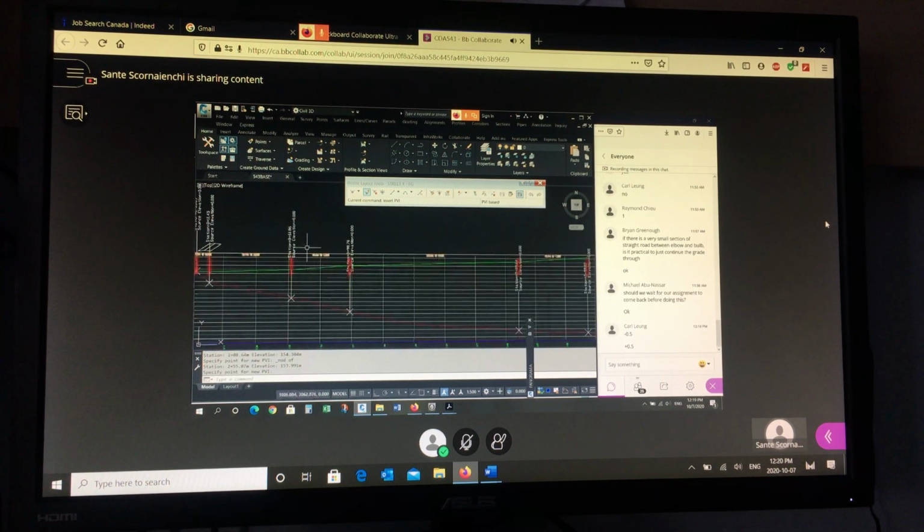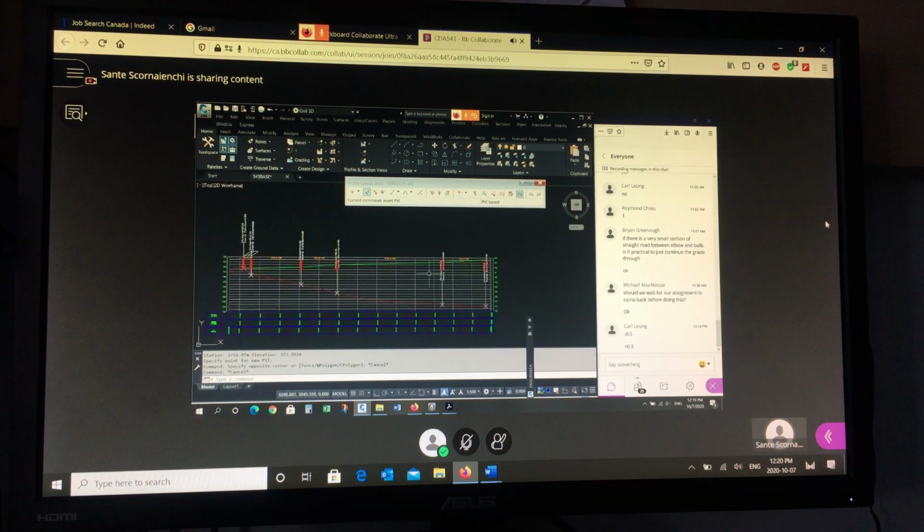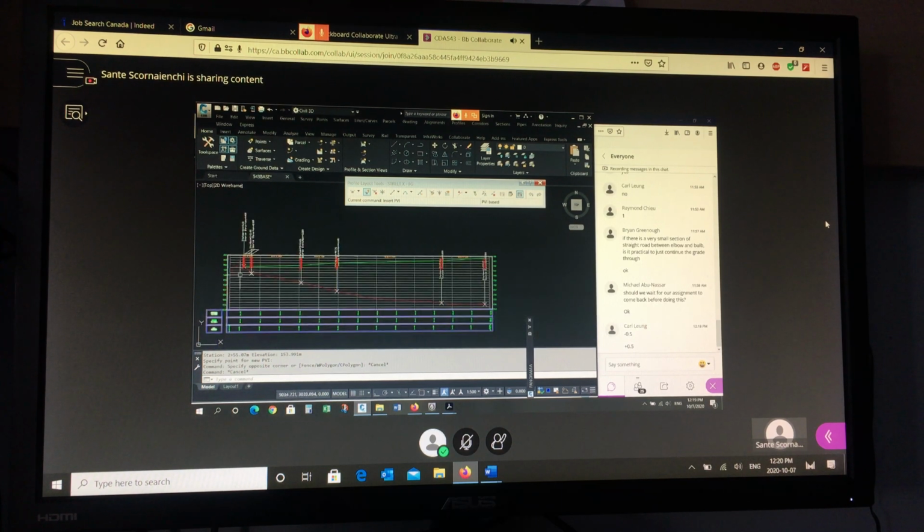If I design the center at 1.5, my gutter is going to be at least 1%. If I design the center at 1.25, my gutter in the cul-de-sac will be at least 1%. So when you look at this at a glance, you might be wondering, what was this designer thinking? Why is he not using 0.5% everywhere? Why change the slope at these locations? Why are these locations critical? Why are they key? Why are they using that PVI location? Why are these stations where they are?